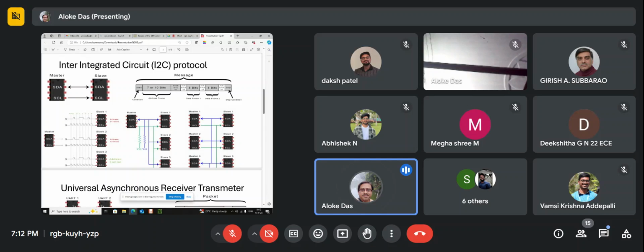This is an output, and an output can go to multiple inputs, no issues. But two outputs cannot be shorted like this, with a simple copper wire connecting two outputs together. In a bus, actually it is connected like that, but there is a catch.